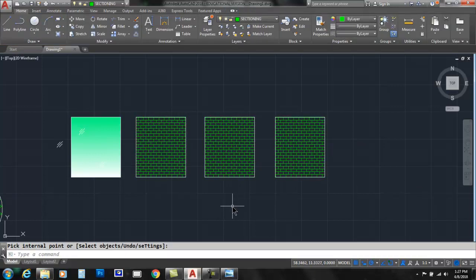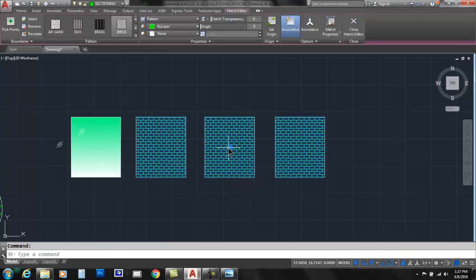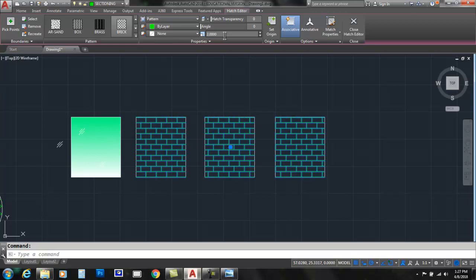Okay, so that's a common thing to do, but there's a negative side effect that we'll get around, but we have to understand what's happening. If I put my mouse back into the shape, all of it lights up, and if I click, it's all seen as one object. So if I wanted to change the scaling or the rotation of my middle shape, I can't do that because they'll all change. Alright, so let's say I go 2, enter. See, I have no individual ability because it's all seen as one.